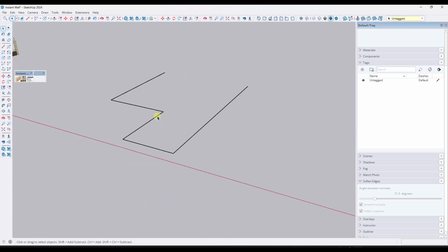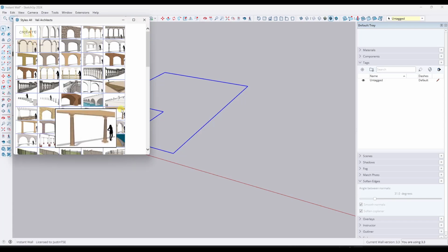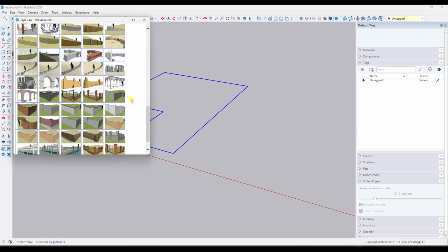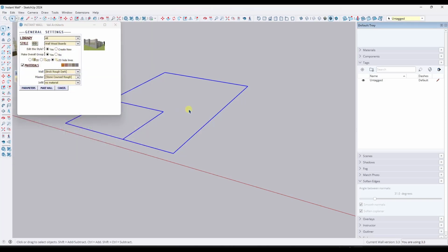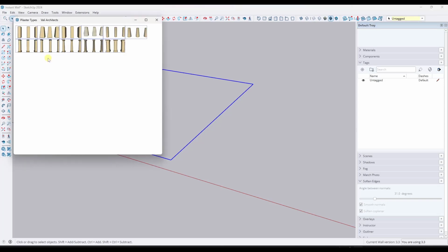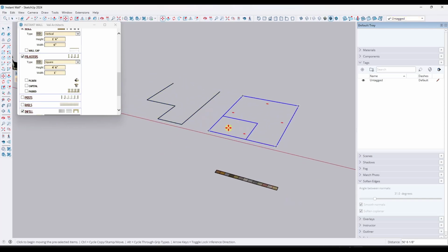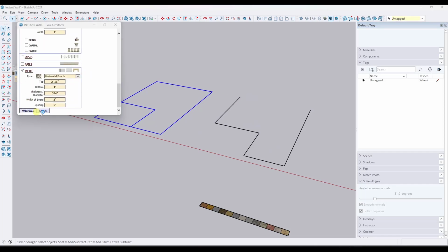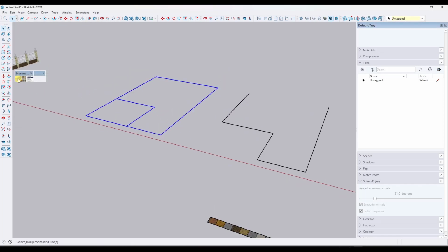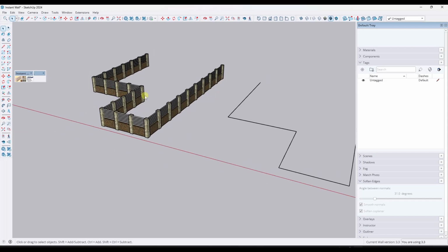And so there's a ton of things you can do with the customization of things like the pilasters of the walls, which are basically the things that show up on the corners. But let's say that we were to pick one of these walls, like this stepped concrete one right here. If you click down here, remember that all of these have different things you can edit about the kinds of walls that are created, but you can also set the kinds of pilasters this is going to create. So if I use the move tool in copy mode with this object and make the wall, it's going to have those square pilasters, and I want to make sure that I've selected the 3D option right here.